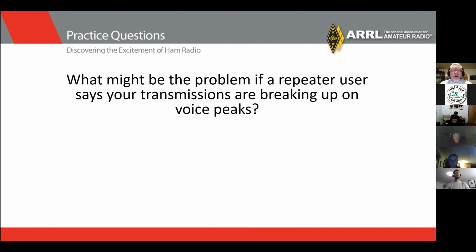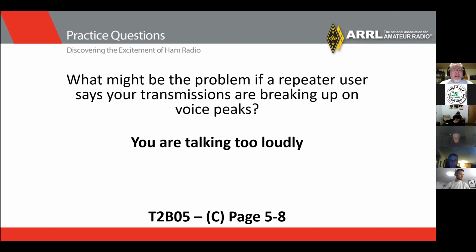What might be the problem if a repeater user says your transmissions are breaking up in the voice peaks? You're talking too loudly. That'll make your voice peaks garbled.